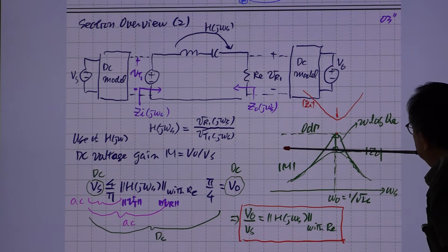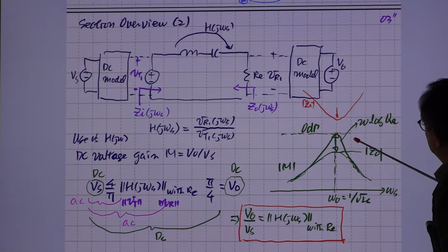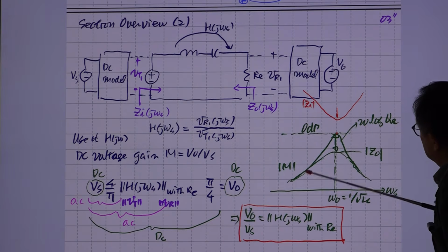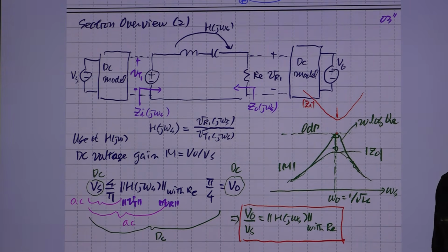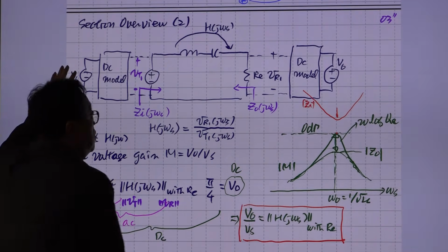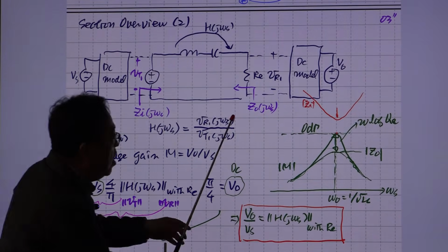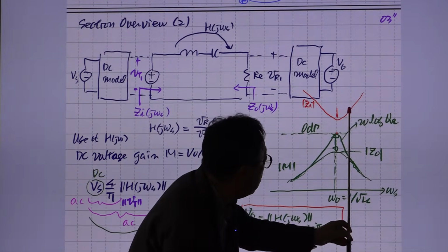And this value is the characteristic impedance of this circuit. And we have a factor of 20 log QE here. So this is the actual gain curve, DC in, DC out. Suppose you put 10 volts here, the output will be 10, right? And somehow you increase the switching frequency up to here.